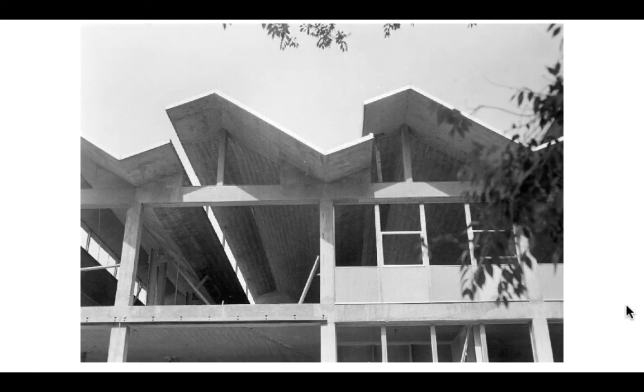Another strategy for doing this is to realize that the folded plate can take on almost any geometry. And so if we really want to, for instance, bring in north light to, say, a factory building, we can design a folding plate that's tuned very closely to that functional need. And this checkmark shape, even though there are more efficient structural shapes that we could use, right? This is pretty far from an I-beam in terms of the efficiency of where its material goes. If you think about what that structure is doing, now it's doing a handful of functions.